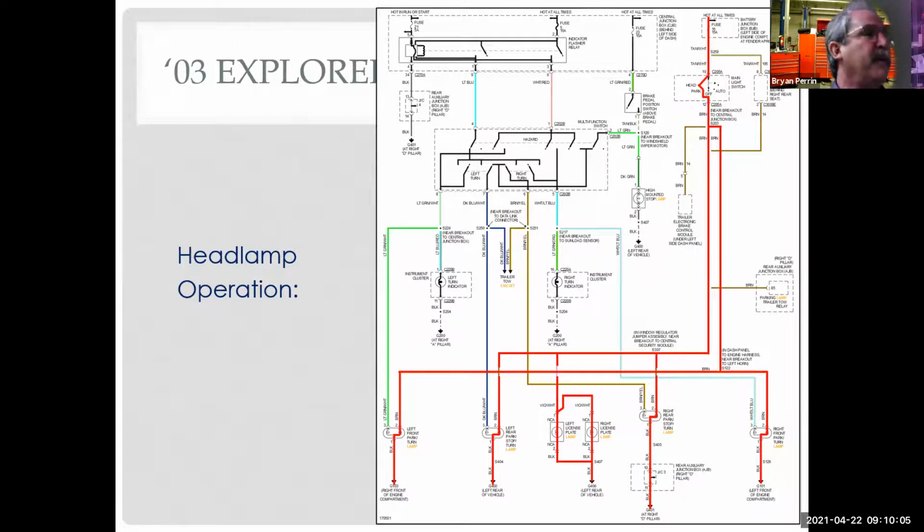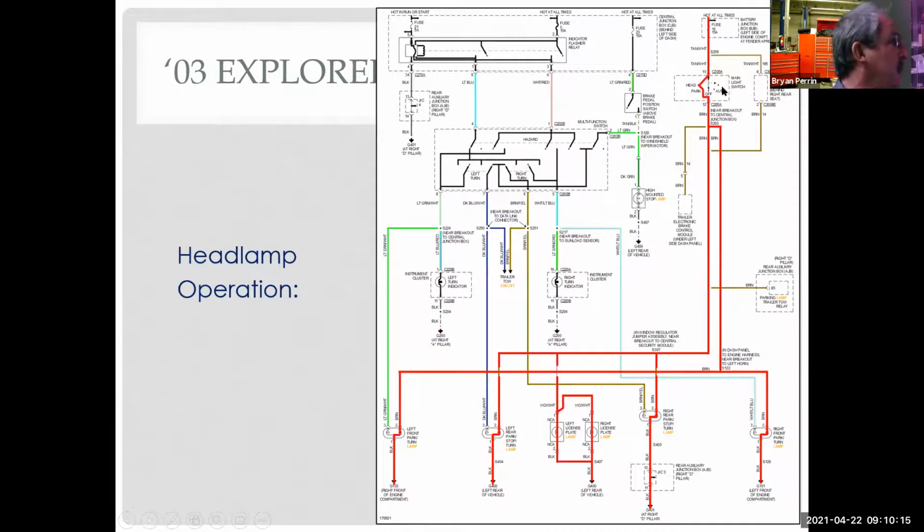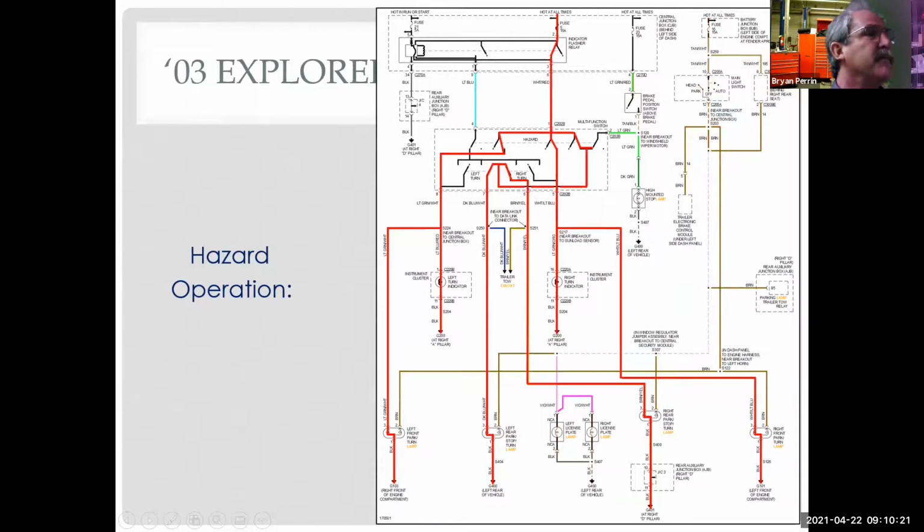So if I back up a little bit here, I have power coming through here, and I have the combo switch, but in the previous case for my headlights, I don't use the combo switch, and I know I have the problem when I turn the headlights on. Therefore, it's probably not the combo switch, because I don't use the combo switch when I use my headlights.